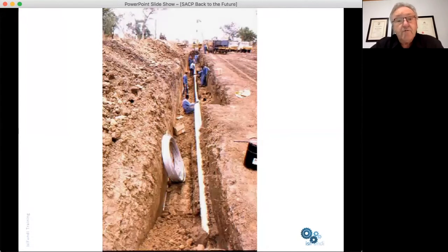Magnesium anodes in the form of ribbon can also be very effectively used in pipeline rehabilitation situations, such as you can see in this photograph, where a section of a pipeline in a rural area was being refurbished. You can see a pipeline rewrapping team in progress. And as the pipeline was refurbished, so the magnesium ribbon was rolled out in order to provide protection.